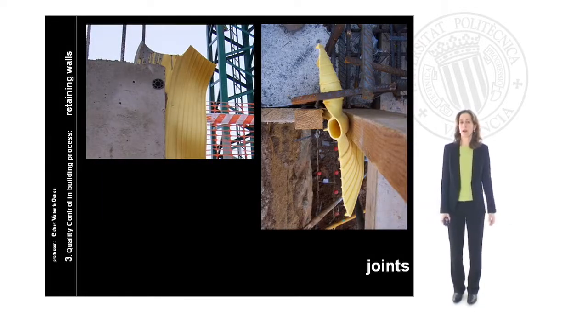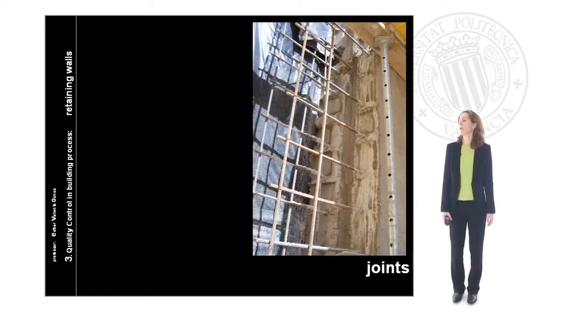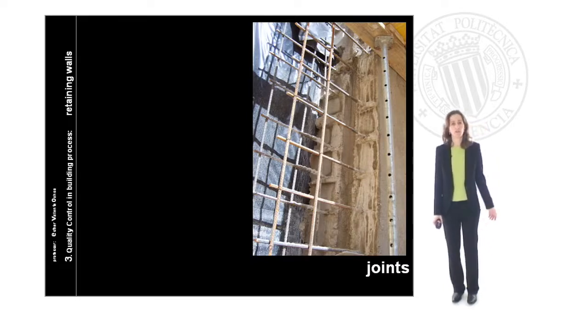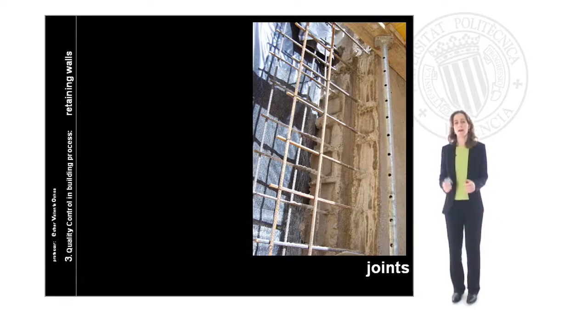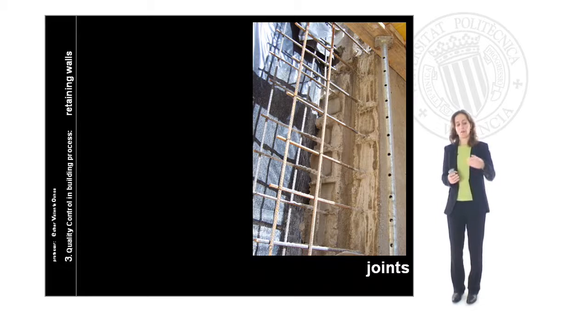Joints, in the case where we have a dilatation joint, use this kind of PVC strip. It is like a line that will guarantee us complete waterproofing between our pieces of wall. Constructive joints have to have a little key, a little curve, with a concavity and convexity that guarantee the resistance and the connection between both concretes with different edges.